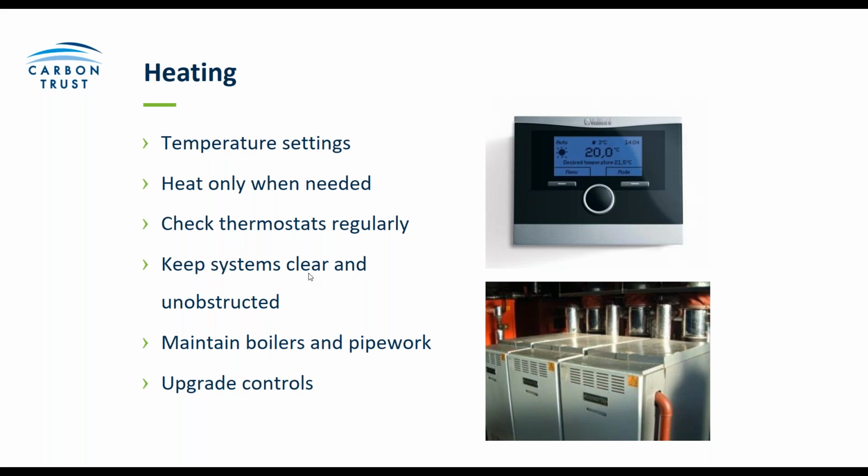Make sure that you keep all systems clear and unobstructed. So for example, radiators and vents, you don't have any equipment sitting in front of them. Also that any filters on external condensing units for air conditioning, for example, are kept clean of dust.